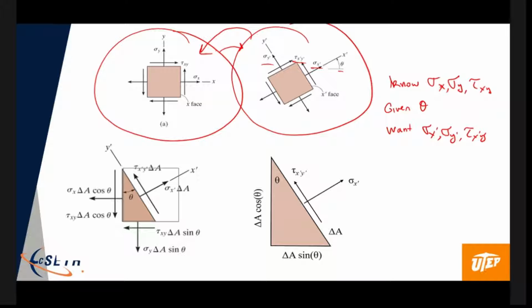Obviously, they have to be related to the components in the other coordinate system because it's the same physical situation. So one way we can do that is if we look at this free body diagram, or if we take a cut like this, where this angle corresponds to the rotation angle theta. So this cutting plane is parallel to this face, and that's what I'm showing down here.